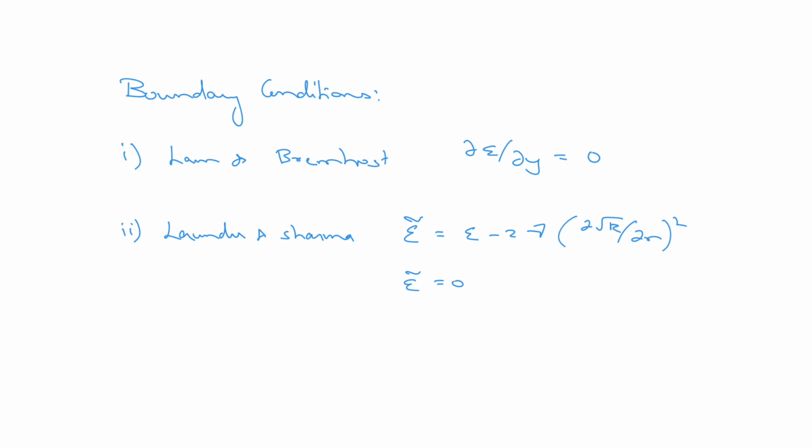For further exploring these wall damping functions, one can refer to books or journal articles, and also to know what wall damping functions are available. Either you can go to your commercial software or open source tools like OpenFOAM and see what damping functions or wall functions are available. You will get to know the varieties of wall functions available, and then you can look into each and every wall function, where it can be used, and what the advantages and disadvantages are. Then you can properly choose a particular function for a particular application.